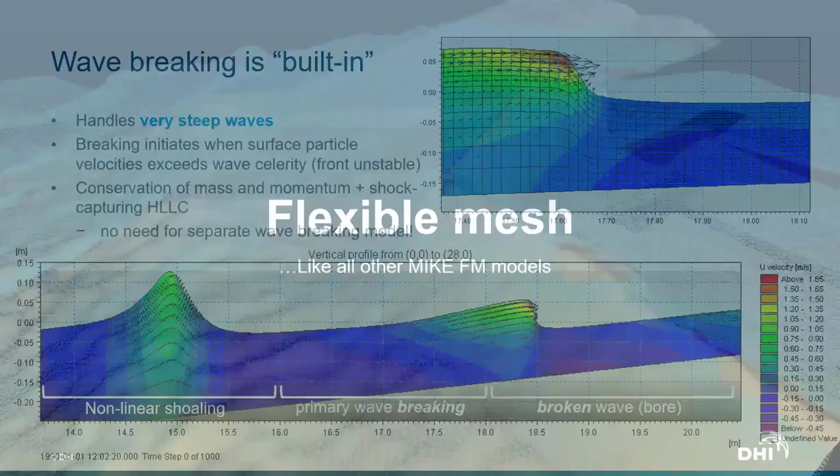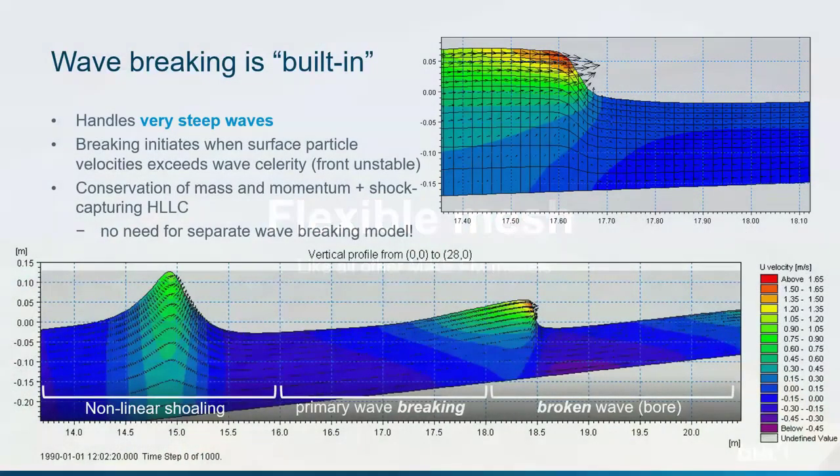Now let's talk a bit more about wave breaking. As I mentioned before, we have introduced this HLLC Riemann solver, which allows us to transform waves all the way through the surf zone, even through wave breaking, meaning that we have no separate wave breaking model as some of our other software.